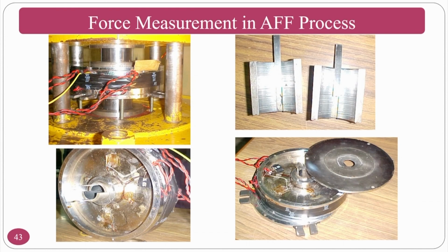If 1 by 1 mm has this much, then since we know the cylinder length, cylinder diameter and other details for the workpiece material, you can calculate with respect to the surface area of the cylinder, that means the internal surface of the cylinder. That way we can calculate the active abrasive particles.